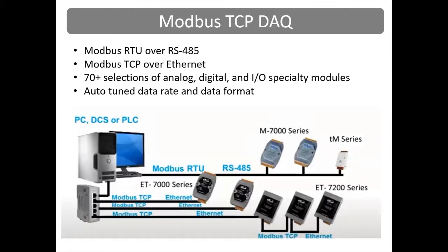Ethernet-based Modbus TCP networks use stateless connections, and it's possible for two or more masters to write to the same register or coil in a Modbus device. A Modbus command contains the unique Modbus address of the destination device, and only the destination device will act on the command, even though the command gets broadcasted out to all devices on the network.